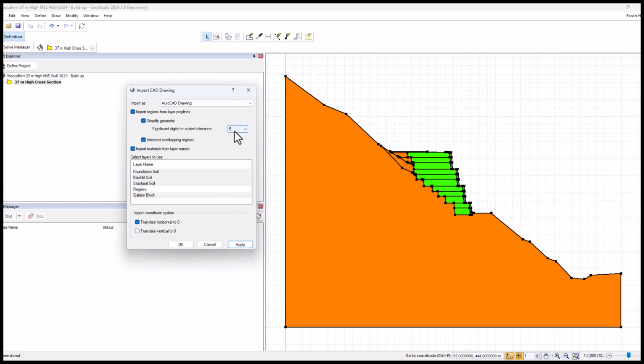The other thing that you can do is just simplify your model. I just want to highlight this, but I'm not going to do that. You can simplify the point segments in your model to reduce the file size and also the constraints later on in your mesh generation, if you wish to do the finite element modeling. So you can click on this and simplify the model.